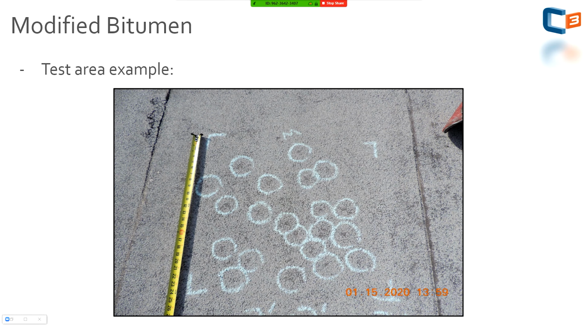A lot of times people will walk up on these and see fastener plates and say, oh, mechanically fastened. But a lot of times they'll mechanically fasten the substrate, as shown in the middle photo there, and that's a square fastener, and then they'll actually bond and adhere the EPDM together to itself, to the substrate, and also at its seams. So you won't see fasteners at its seams. However, to add a little more trickiness, sometimes there are hybrid systems. Sometimes you have adhered EPDM that might go 10 feet in from the perimeter, and it might be mechanically fastened in the field. Or you might have adhered parapet walls and a mechanically fastened field. So just look for those fasteners.